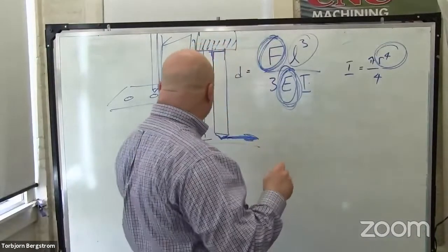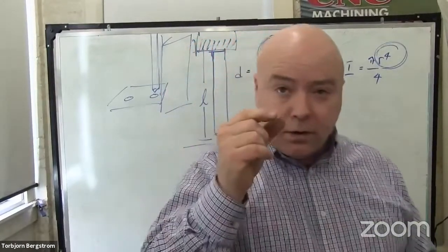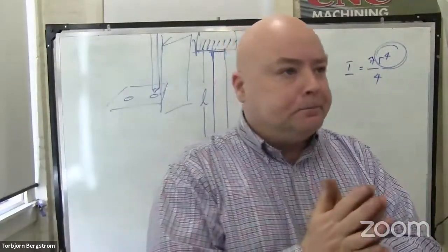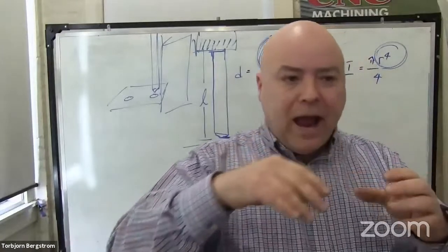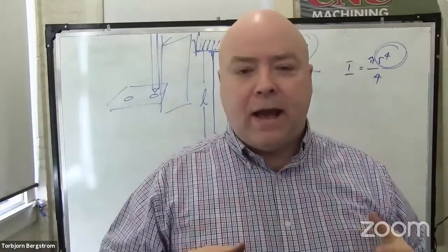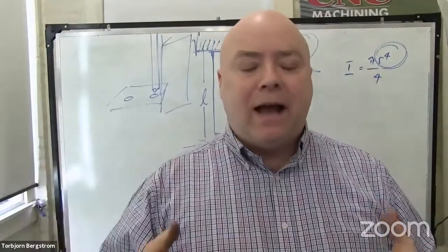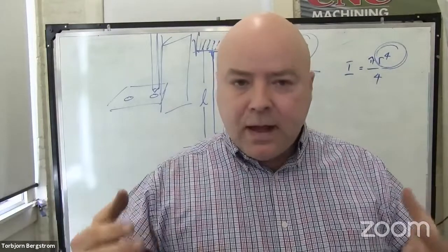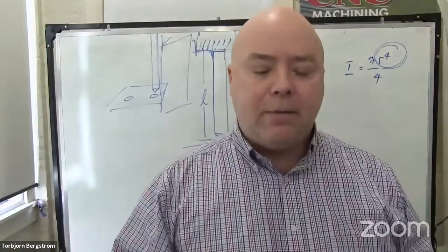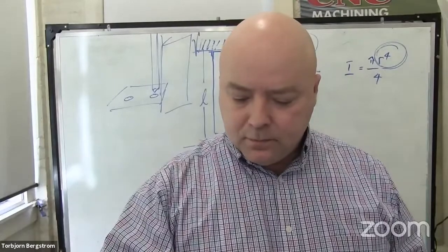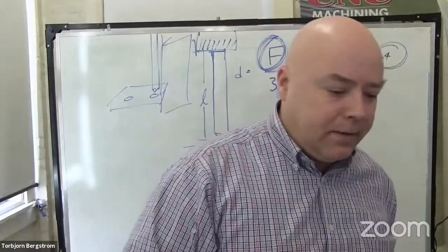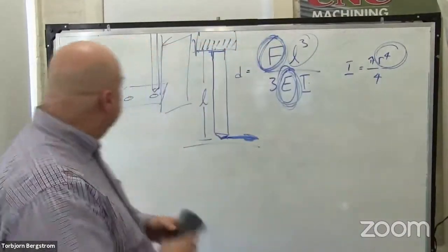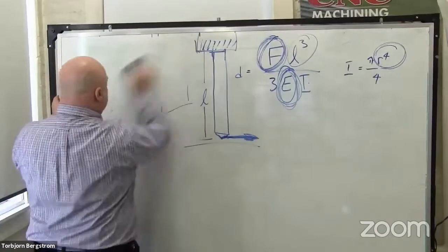Even though the depth of the drilling operation was short, the length of the tool in order to reach the bottom of the hole was long. So when you have a long, deep hole like that, if functionally you need that, then it's okay to have it. But if you don't need it, then you should use a larger diameter hole so that you get a smaller length to diameter ratio. What if, and I see this all the time in parts that we do in the lab here.